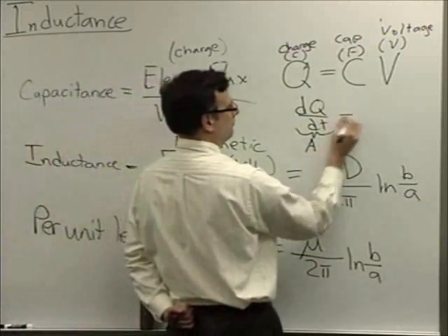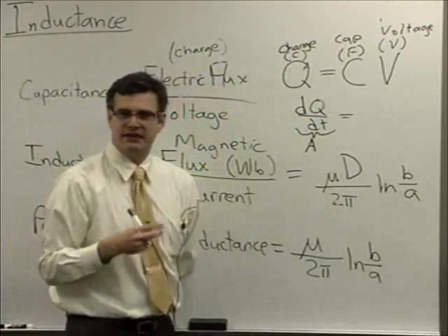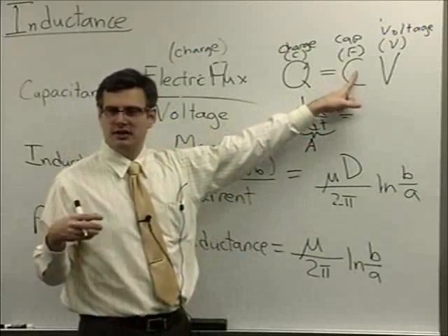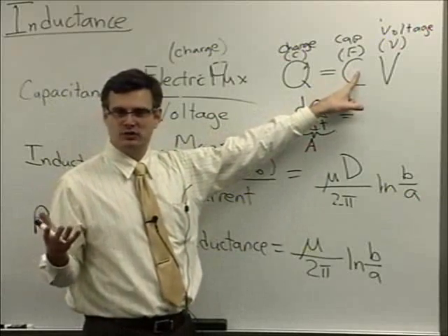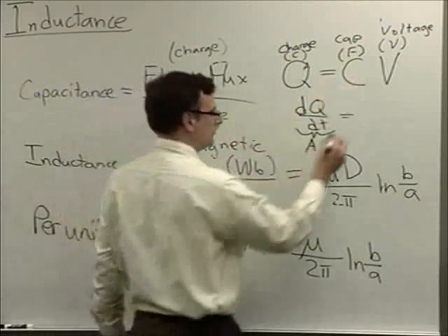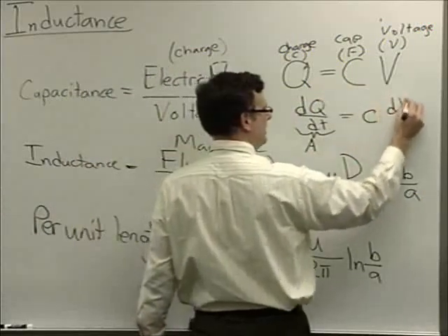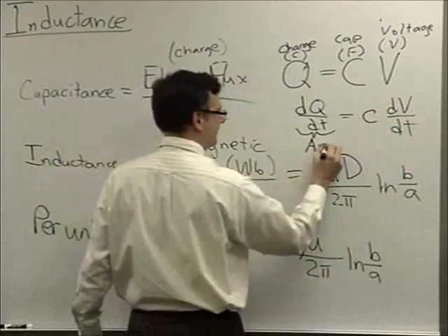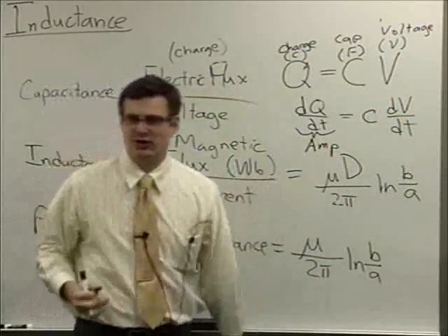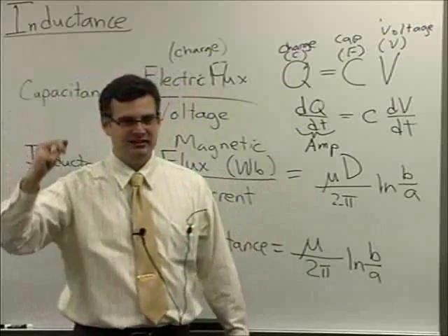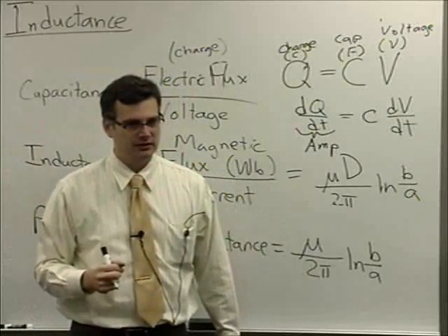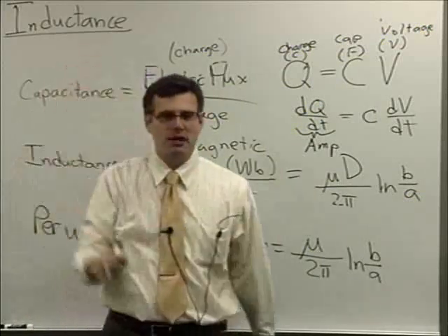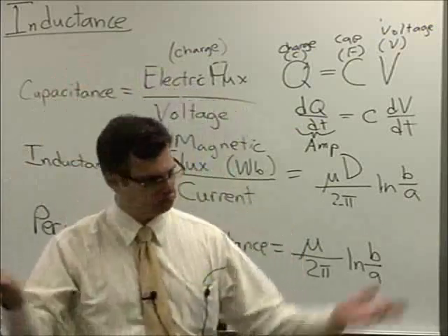And that is equal to, well, normally I'd have to chain rule this thing, right? But if the physical problem isn't changing, my C is a constant. That's what we've been saying all along. Capacitance in a system is constant with respect to the geometry and the material. So I can just take this in and write dV/dt. And lo and behold, I have my basic fundamental circuit relationship. I is equal to C dV/dt. Change the voltage with respect to time. That'll give you current flow to and from the two pieces of metal in the capacitor. Very straightforward.